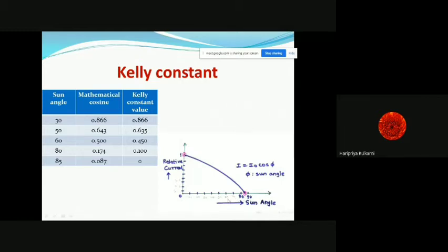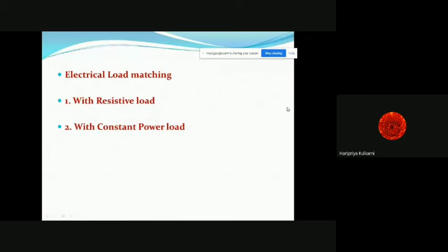So this is the angle made. I mean, if we make the panel fixed at say 0 degree, it will face, so it will be vertical, right? Suppose the sun is coming from the extreme right. So here is the sun and we want to face it to the panel. Then we will keep the panel vertical. At that time, the angle will be 0 because the sun is facing the panel. And if we make it stationary and we do not move it, then definitely at 90 degree, it is not going to catch any power and the total current will be 0. So from that angle it is given, but that's why we are tilting our panel to get the maximum solar extraction. Okay. If you have any doubts, you keep it aside. We will solve it at the end of the session.